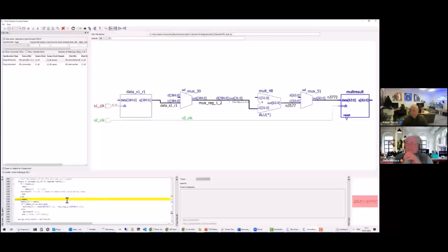But as Dave said in his talk about it, again, when we introduce this, we're making changes to the RTL. So if we've done lots of verification and validation before we get to this point, then we've got to rerun that to make sure that we've not broken anything and that the knock-on effect is not significant. So we want to do this as early as we can in the design, just like finding any issue in the engineering side of things.